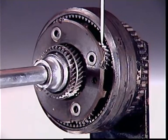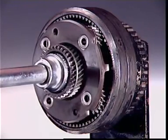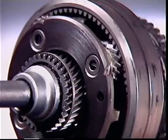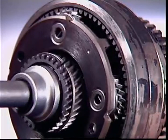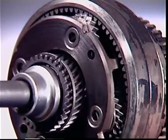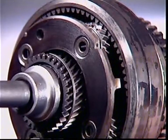This means the planet pinions are always in mesh with the sun gear and the ring gear. In operation, their motion is described as either walking or as idling. Walking means that if either the sun gear or the ring gear is held stationary, the alternative driving member rotates the planet gears on their pins. This turns the planet carrier in the same direction as the driving member.